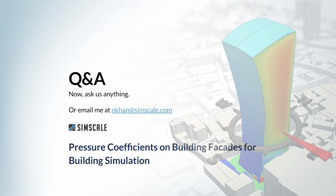Is the approach also applicable to finding pressure coefficients to calculate structural wind loads on the buildings? Yes, absolutely. You can reach out to us and we can share with you some instructions on how to do that. But once again, that's very applicable to that validation case as well. What will be the probable difference between the wind tunnel and the CFD analysis? Providing we follow all the best practices, then actually they would be very, very close, probably under 10% if you did the mesh independence study.